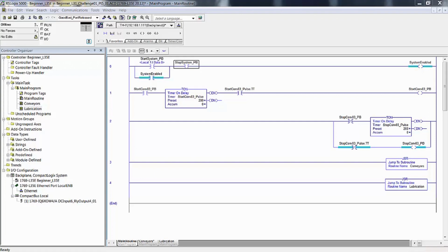Okay, type of photoelectric sensors and placement, as I said, is an extremely important aspect to all control systems that require optical sensing. In the manual I show you the 3 types of photoelectric sensors: through beam, retroreflective, and diffuse. The through beam gives you the most deterministic object sensing because the object blocks the beam as it passes between the transmitter and the receiver, and then the object is sensed.